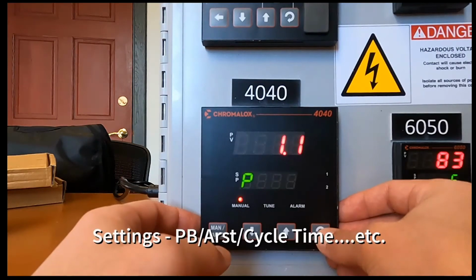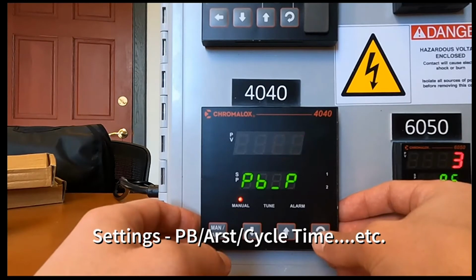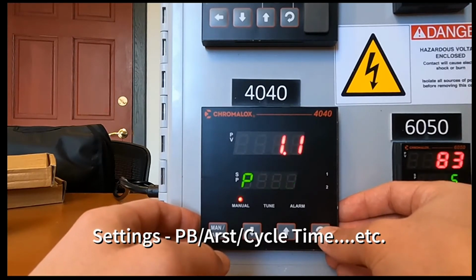That's pretty accurate, yes. And too, if there's a differential, say your process is 100, but you have to set it at 110. You don't want 110 on the controller. You're going to put 100, and you put the offset in there to deal with that.